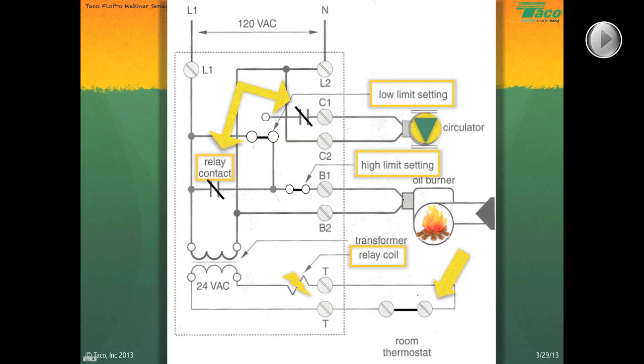It's basically what it is. It's a simple man's domestic hot water priority. This would happen during the heating season if we had a major call for domestic hot water, and during that call for domestic hot water, the boiler temperature dropped below the low limit. Well, now what we're doing is we're saying, you know, sit, stay, heating system. We're not going to give you any heat. We're going to focus everything on making domestic hot water, and we're going to do that until the boiler temperature gets above the low limit, above the differential above the low limit, let's say. If it does that, then we go back like so, if that makes sense.